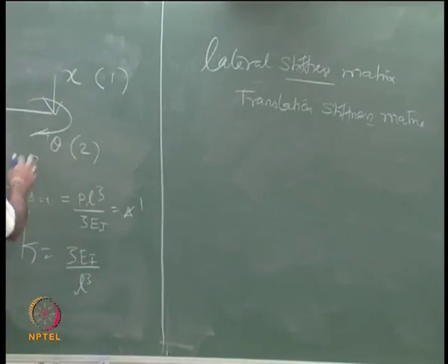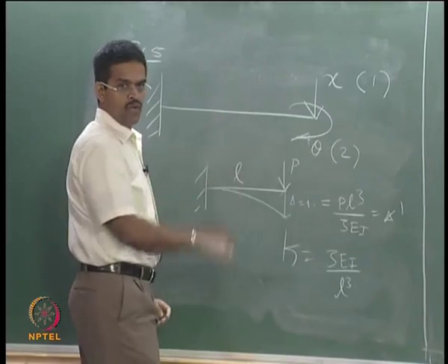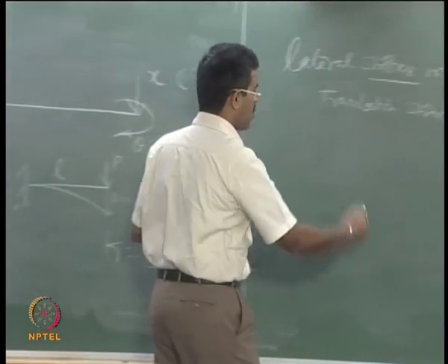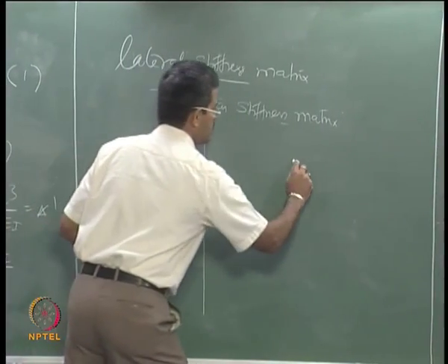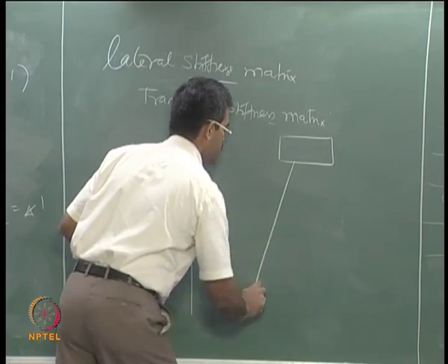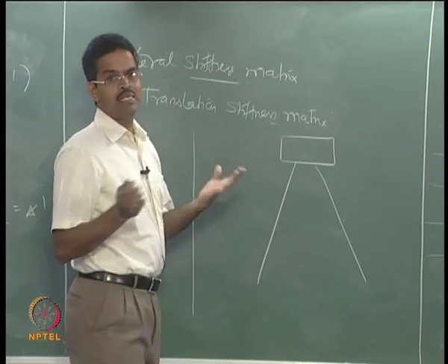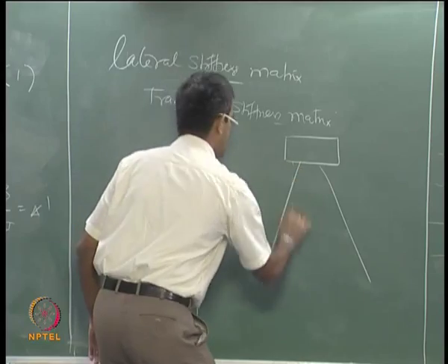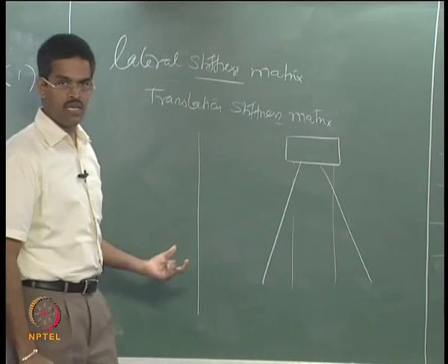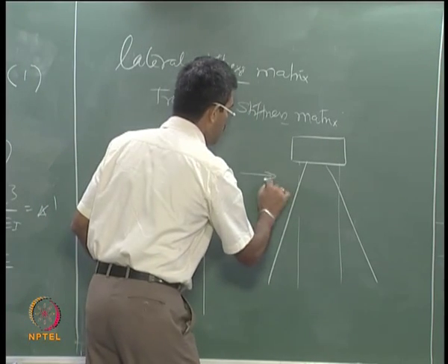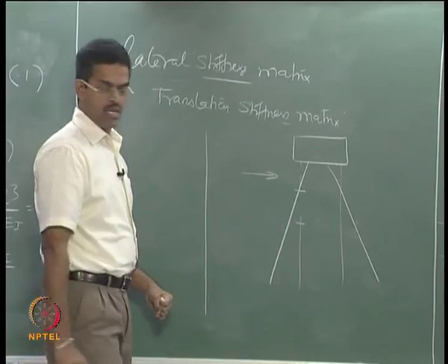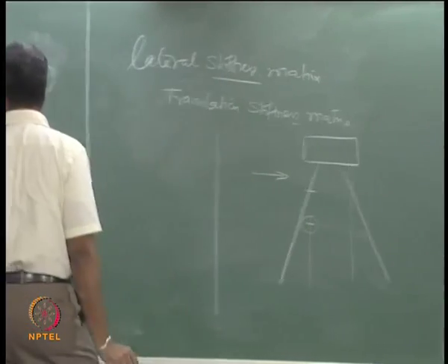Look at this as a problem of a column of an offshore jacket structure. I have a column, let us say this is my jacket platform. I am idealizing it, taking a simple example of a vertical member for understanding. I have a lateral load, pick up any segmental member, assuming this boundary condition as fixed.